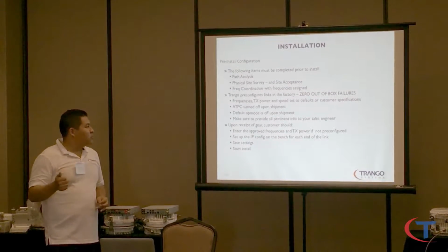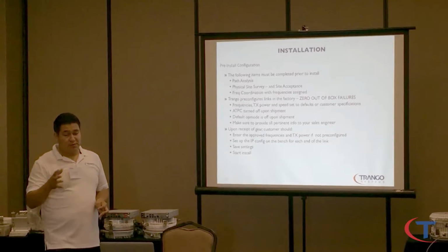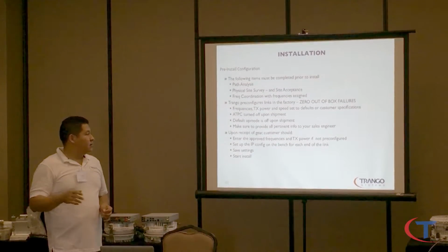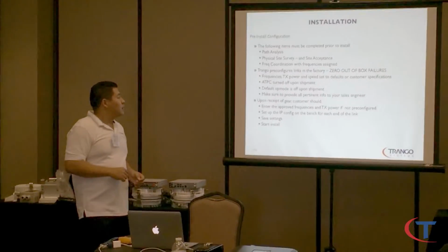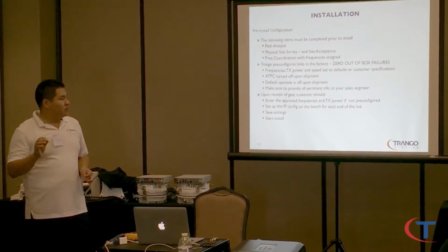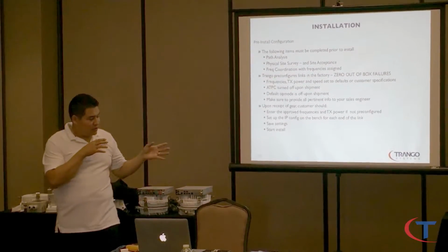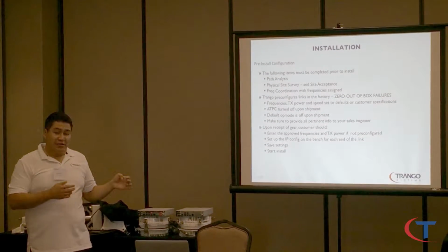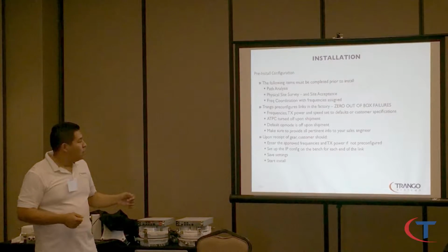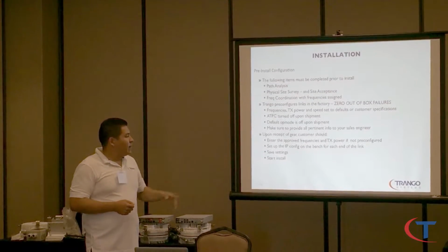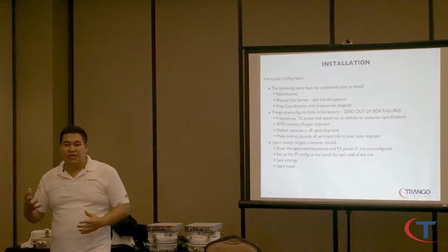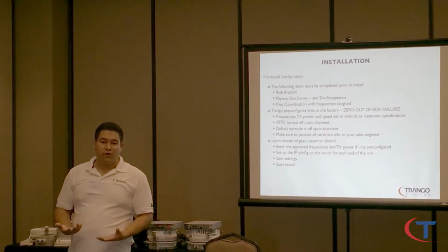Frequencies, TX power, and speed are set to defaults or custom specification. ATPC is turned off upon shipment for the alignment process. Default output is off upon shipment, so you can actually connect the ODU. It's going to be ODU power off, and it's not going to transmit at all. Make sure to provide all current information to your sales engineer, so Ray has all the information he needs to help you build your link.